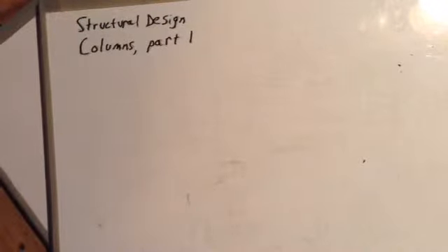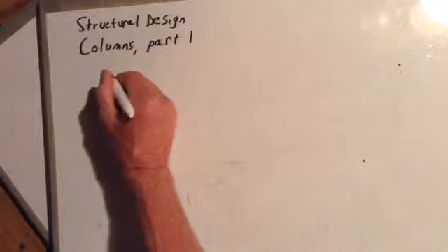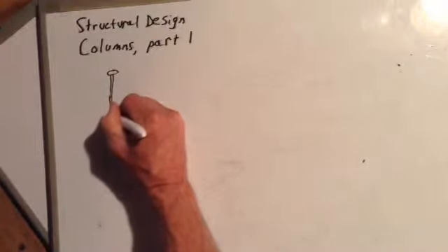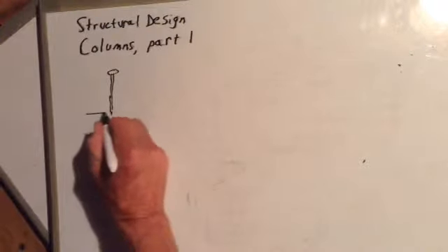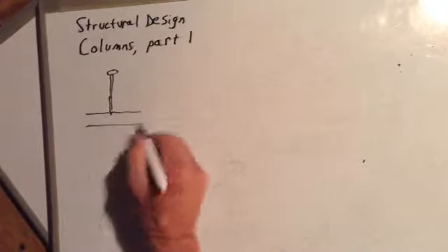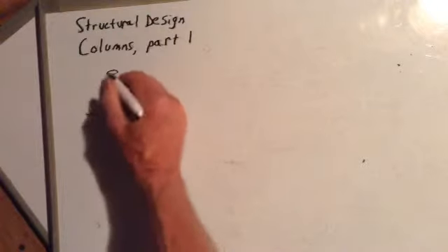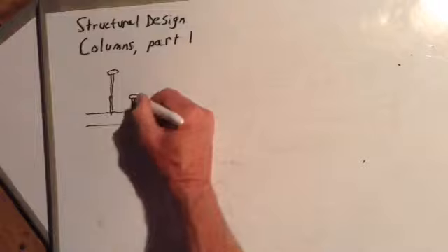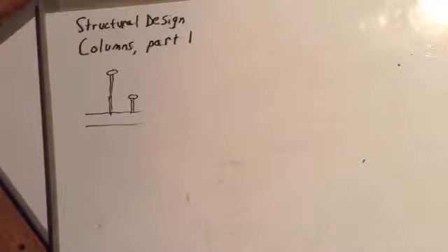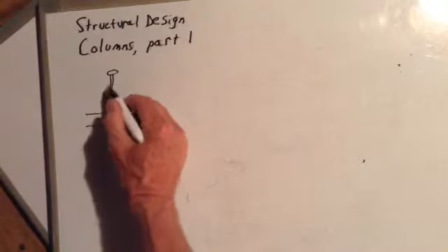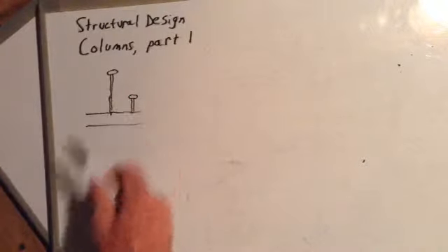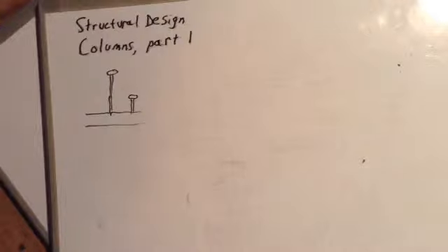Okay, a nail. Let's say here's a nail head. There's a nail. Okay, and there's the point of it. And here's a board. Well, that nail has a much longer column than a nail that's already been hammered into the board. And the longer nail, the nail that's just getting started going in the board, is much more likely to bend. Long columns are weak and short columns are strong.